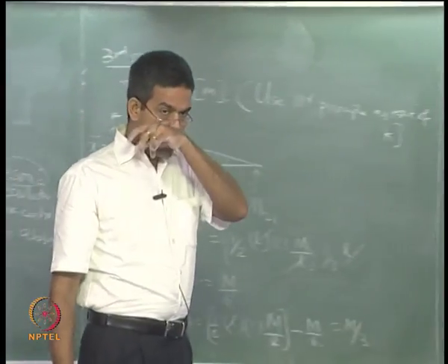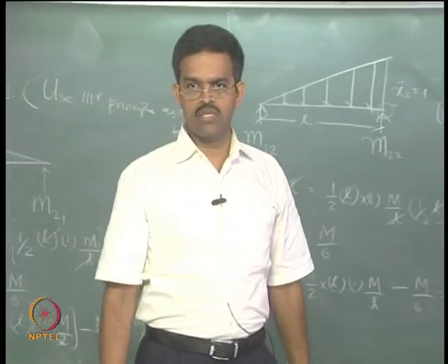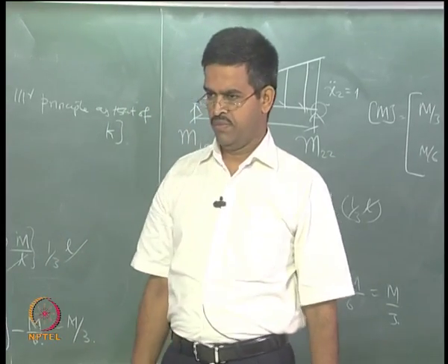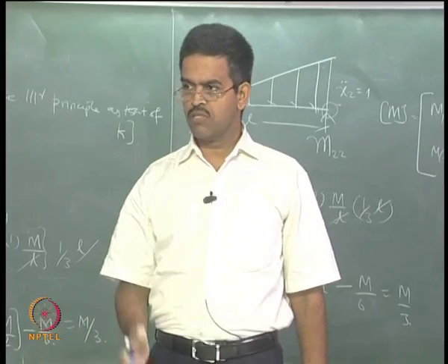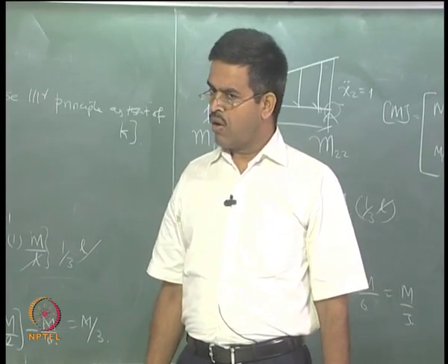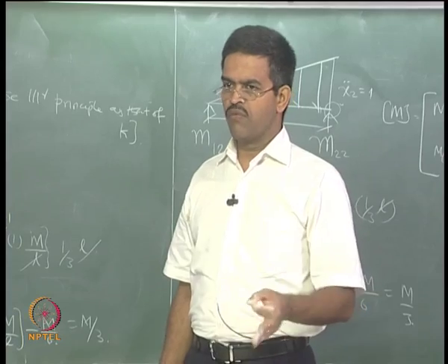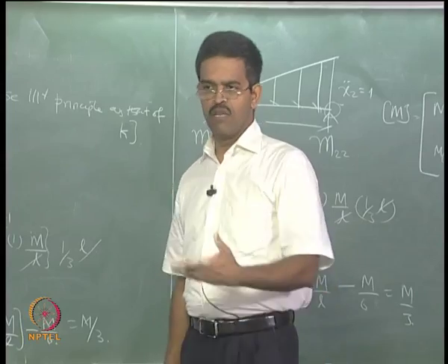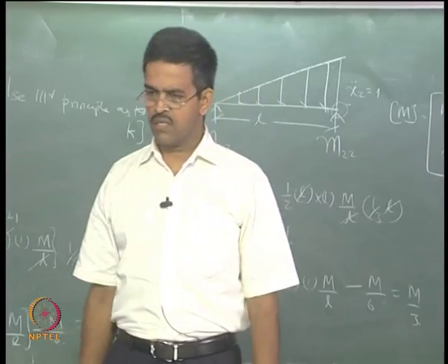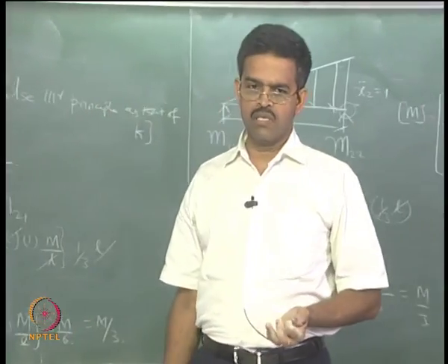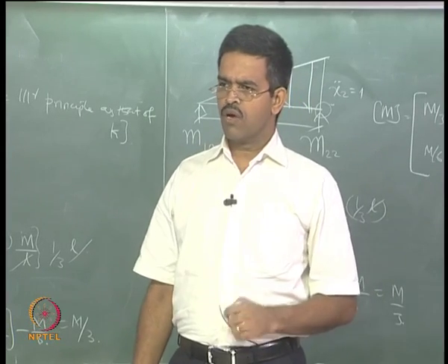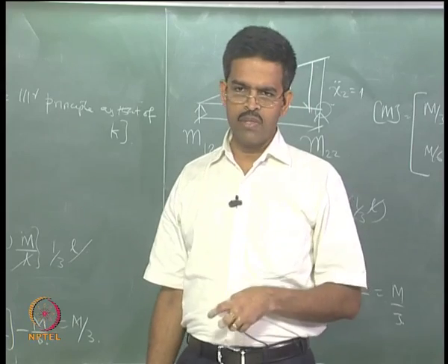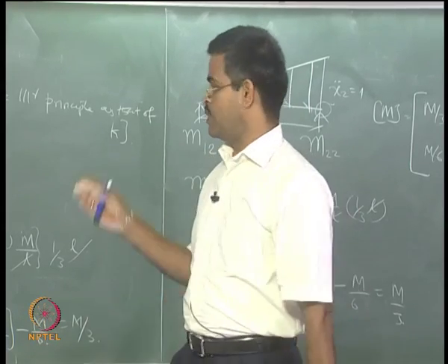This also proves very interestingly one thing to us, that the degree of freedom is nothing related to the mass point. Here it is 2, whereas the mass is concentrated only at one point. So all confusions related to degree of freedom being the point where the mass is concentrated are all gone. We have already defined it very carefully and clearly that it is nothing related to mass concentration at lumped mass points, but crudely one can remember that wherever the masses are lumped, these are the number of degrees of freedom, but not always, as you see here.